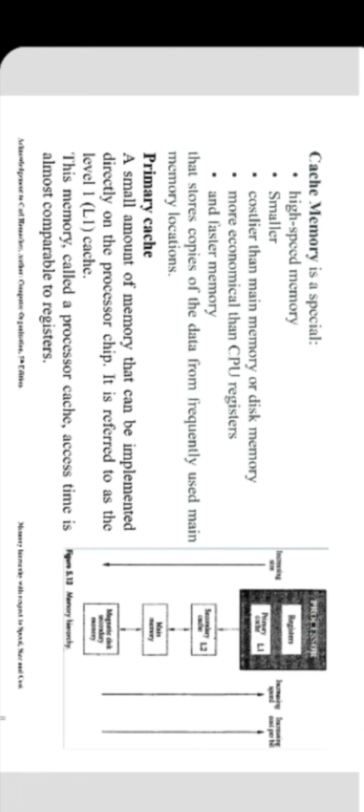Hence, registers, because they are very costly, are made available in small number, but a comparatively little bigger primary cache is provided, but not more when compared to secondary cache, because the on-chip space available is less.